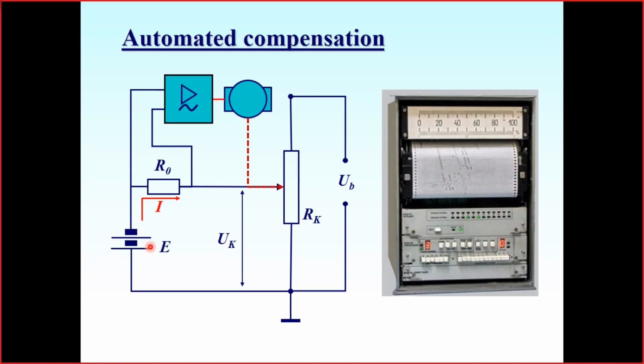Nowadays it's not so actual for thermocouples, because we have amplifiers with quite a high input impedance to work with thermocouples, but it may be thermocouples, it may be some kind of chemical devices. So it means devices that provide voltage but couldn't provide a high current. And to measure this with as low distortions as possible, we may use these potentiometers.